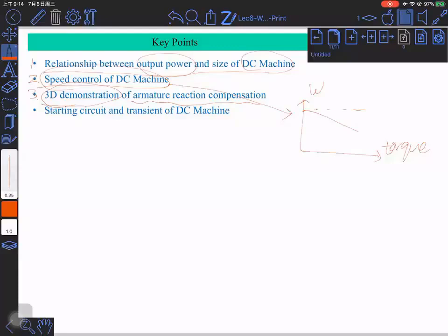The second is that armature reaction causes a generally decreased field flux. If the flux decreases, it is going to increase the speed and the armature current. If the armature current increases, it further decreases the flux, and this trend goes on, causing instability. We said that armature reaction can be compensated by the compensating winding, and with it we solve both of the problems we just mentioned.